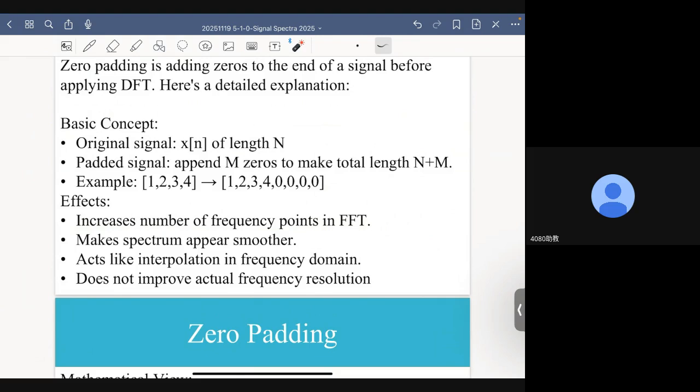Now, if I want to represent this signal from a different perspective, using a frequency domain representation instead of a time domain representation, remember, we are still dealing with the same signal. So if in the time domain I have 100 pieces of information, in the frequency domain I still have 100 pieces of information, no more and no less. So the more data points I have, the better resolution I have in the frequency domain.